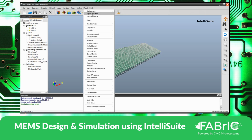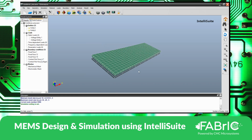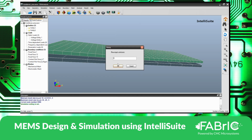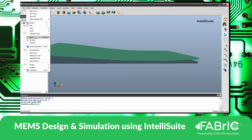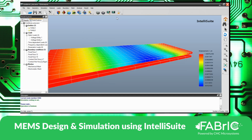Fine. So for the deformed shape, I would increase the input scale factor because the deformed scale is too small. So this is the deformed scale. If more is required, it's always recommended to have a better deform scale. And for better accuracy, I think a finer mesh is required. Else you can always take this Z displacement.